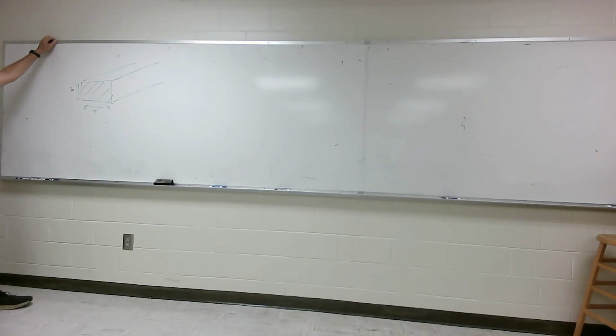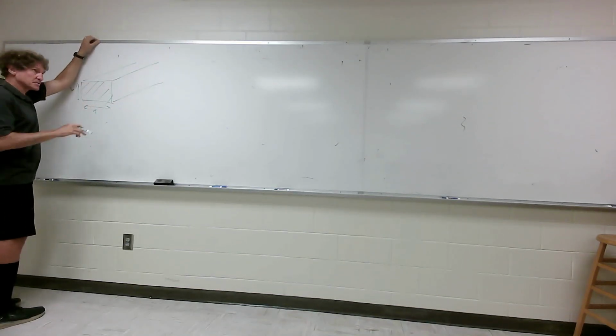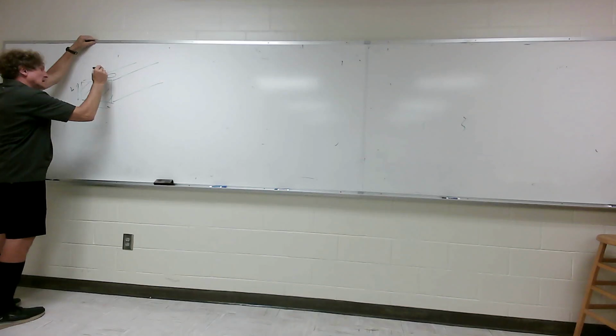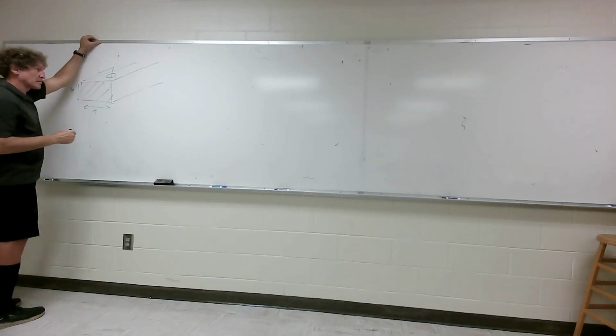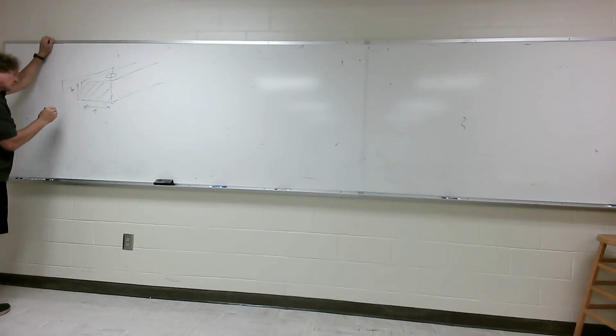Do y'all follow me? So there's only one way for any power or information to go. It's that way, in the Z direction. And if you cut a hole in the top of the guide, and we haven't gotten to antennas, so this is a bit much, and you would drop an antenna down there, that antenna is going to allow power to be coupled to the waveguide.